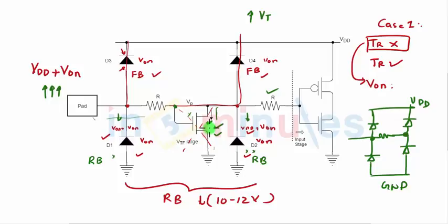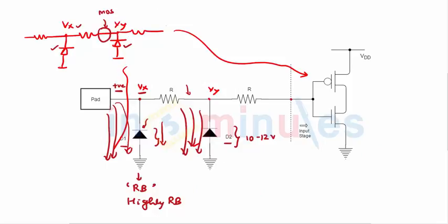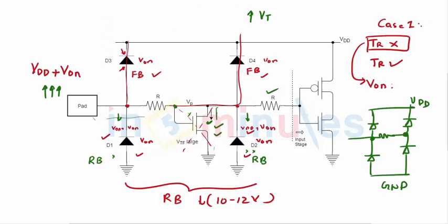So what we studied here was, one protection is where you just have your diodes, correct? Between them you put resistors. This is one protection. Additional protection we went ahead and saw was this one. Then we went ahead and saw another additional protection where you put a transistor here with a high threshold voltage. The other one could be to remove all the diodes, just let the resistor and this transistor work, all different combinations of the circuit, which is used to protect our input circuit from electrostatic discharge events. So I think with that we understood input protection circuits.